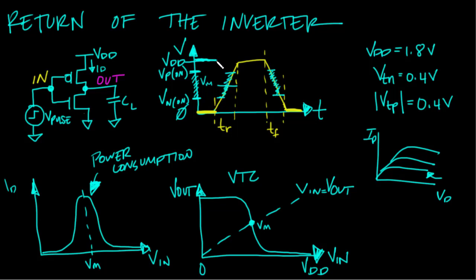I don't have the maximum drain current that I could possibly have because I have a pretty low VGS. So my NMOS might try tugging down on this node, but the NMOS really might not get that far, because the PMOS is still all the way on and at the same time working against the NMOS device. And that PMOS device stays on until this point in time right here. So maybe the NMOS device starts to tug this node down a little bit, but it really could have a hard time tugging that node down until this point in time where the PMOS device turns off. Because remember, anything above this point, the PMOS device is off. And now the NMOS device can start pulling the node down. Now we're going to drop from Vin equals VDD, we're going to drop down to 0.